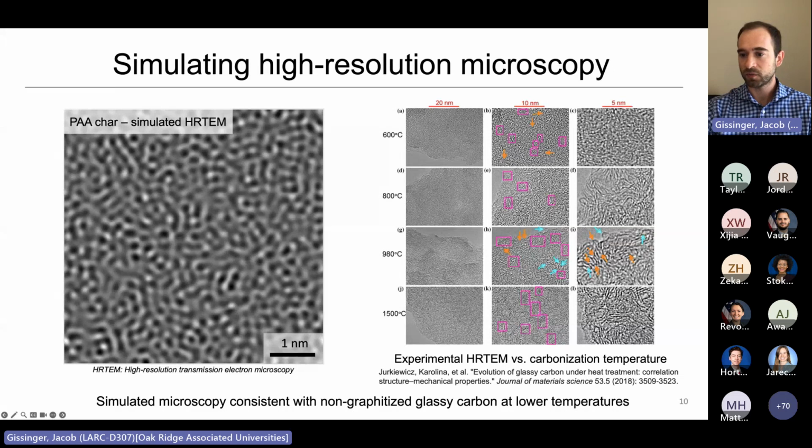So if you look at the far rightmost column, you can see notably an increase in the amount of small crystallites that are being formed, which are characterized by these small parallel regions, lines that you can see in these TEM images. And that is basically the nucleating bits of graphite that would then increase and grow with more time or higher temperatures. So this is another way to confirm exactly where we stand with respect to comparing our experimental samples with our simulated version.